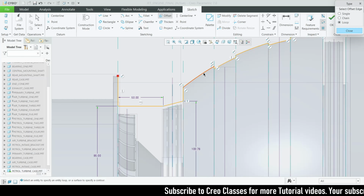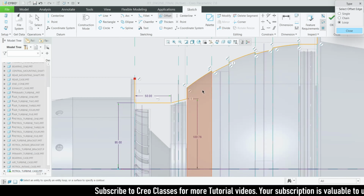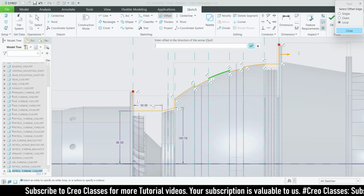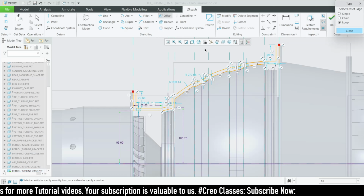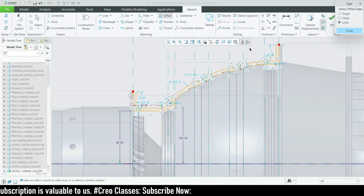So loop feature, select this entire sketch. Yeah, I can't see the arrow mark. Select this, and you can see it is towards outside, but we need it as an inside. So I'm going to click on negative value here, -5. So this -5 you can see here. Okay, so this is the value for this.